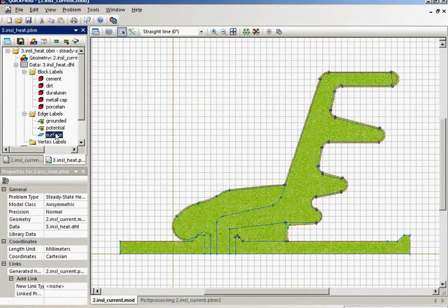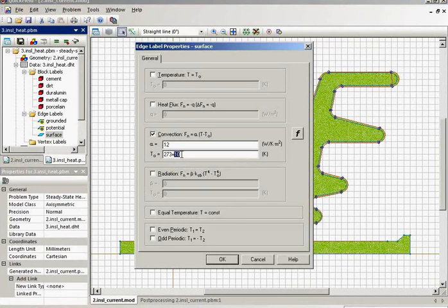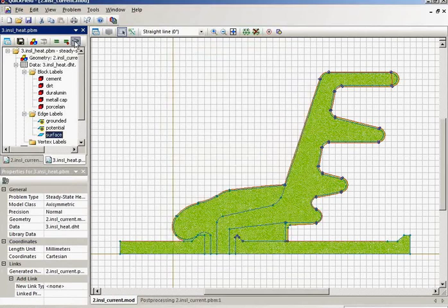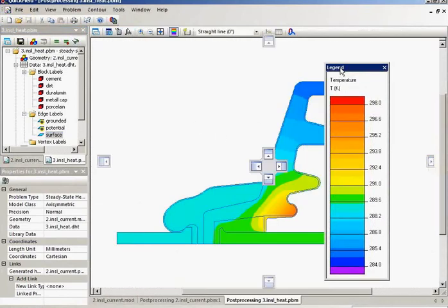So again, the rainy day, humid air, some current flowing on the surface of the insulator. The temperature outside is only 10 degrees Celsius. Now let's calculate the insulator temperature. The insulator is heated by the leakage current. So you can see the insulator temperature is about 25 degrees Celsius, and the air temperature is 10 Celsius.